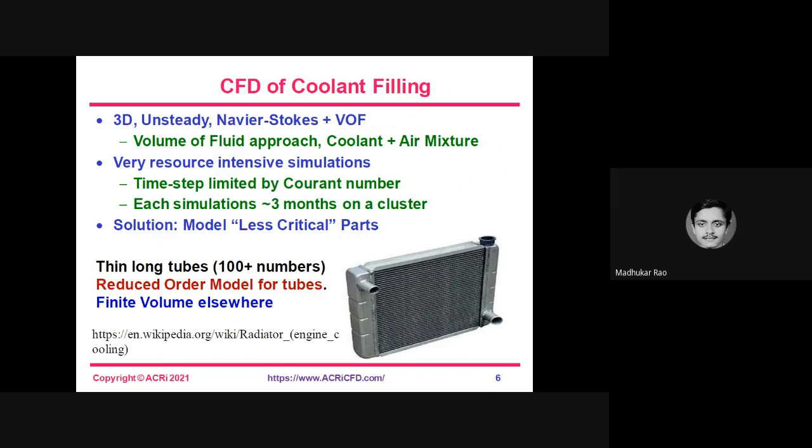So basically, the CFD of coolant filling was being simulated by the client using 3D Navier-Stokes with turbulence models and the VOF approach. And this was very resource intensive. Because the time step was limited by Courant number, each simulation took place on a cluster for about 3 months or so. That's what I heard. And so when they approached me, I knew that if I tried the same thing, I would get more or less the same result.